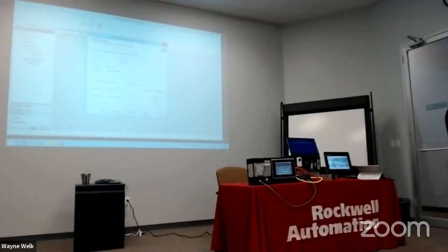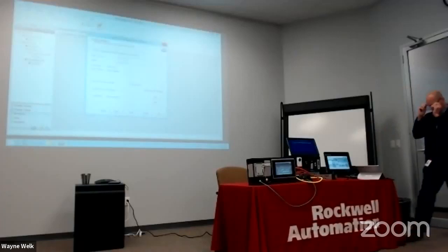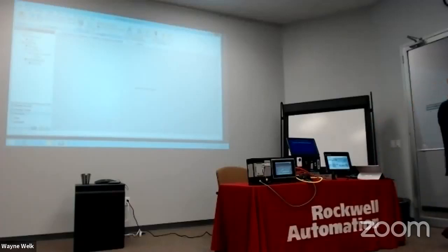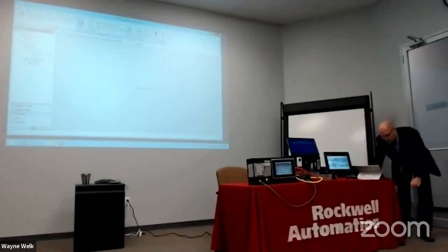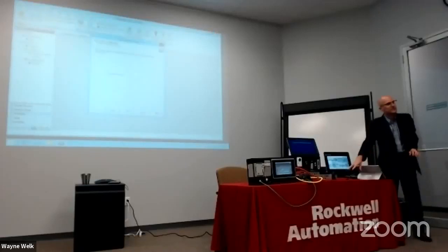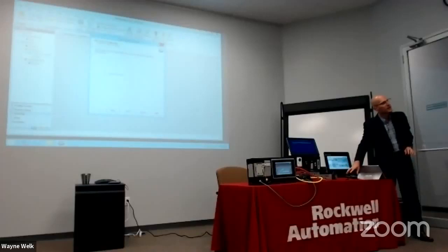The only thing that's changed here, soon to be, is the hardware. I'm not going to change the content that's being delivered, any of that. And before I answer the question, no one's asked, so I'm going to tell you why I'm delivering it that way. Again, Chris talked about hard coding, Thin Manager ready, BIOS, all of that. I'm using what is called PXE, pre-execution environment. There's a PXE server within Thin Manager. You're communicating there. It's a checkbox right up here. By me checking that, it's allowing it to look for a device that has no OS. This is not a Thin Manager ready device. This is an off-the-shelf device that you have, or a computer.